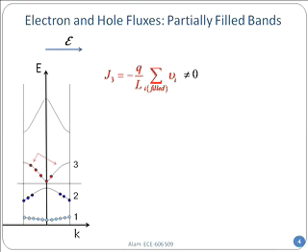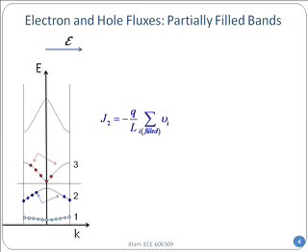Now let's focus on the blue one. What happens in the blue one is, again, of course, if you apply an electric field, but remember, these are electrons, minus q charge, but these have negative effective mass, so they will move in the opposite direction. And as a result, when the electrons in the valence band move in the opposite direction, correspondingly there will be an asymmetry between the plus state and the minus state, and together, once again, there will be a net current. But there is a very nice way to think about this, and that's something called a hole. Let me discuss that.